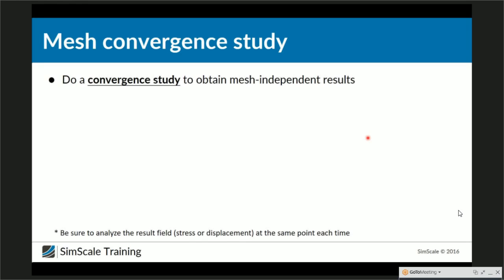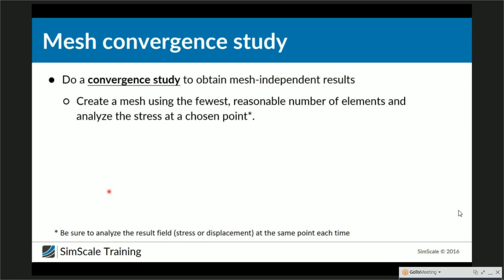For example, in this example, we wanted to test the under truck protection, a kind of bumper. And for this simulation, we needed some faces to apply this boundary condition. Therefore, it's necessary to split this surface into some subsurfaces so that we can apply independent boundary conditions for each of them. And last but not least, fuse as much as you can.